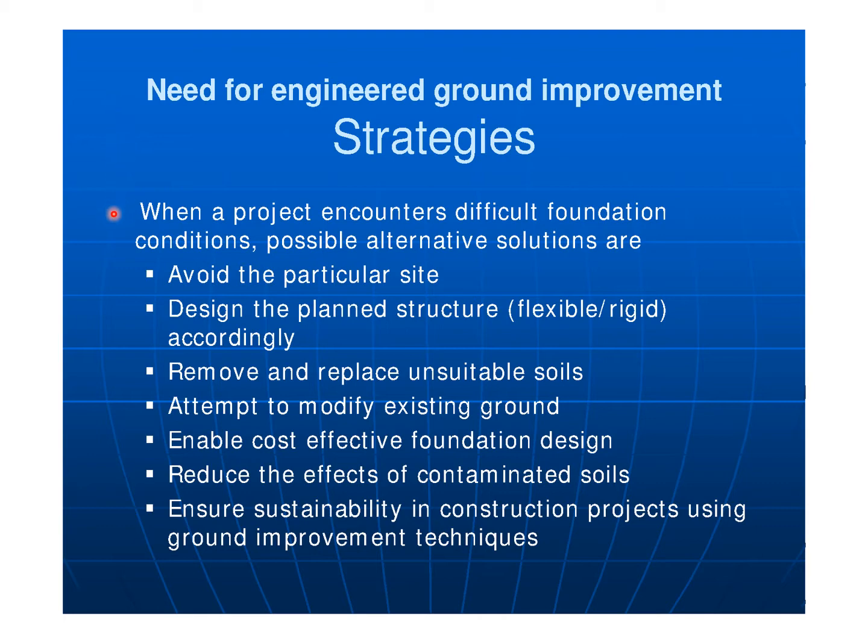When a project encounters difficult foundation conditions, possible alternative solutions are: avoid the particular site, design the planned structure flexible or rigid, remove and replace unsuitable soils, attempt to modify existing ground, enable cost-effective foundation design, reduce the effects of contaminated soils, ensure sustainability in construction projects using ground improvement techniques.